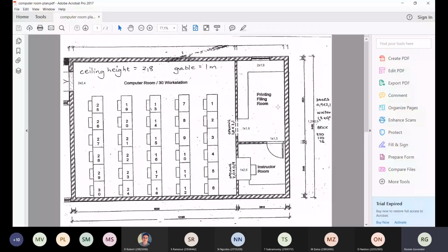Right, you'll notice now for the lintels, because it's what we can refer to as a double skin wall, a lintel is the width of a single skin. A lintel is the width of this internal wall. So I'm going to need two lintels there, which will sit butt to butt, in other words, next to each other. In this instance, remember I told you that this window is 1.2 meters wide by 0.9 meters high. Now I need 300 on either side so that I get enough.